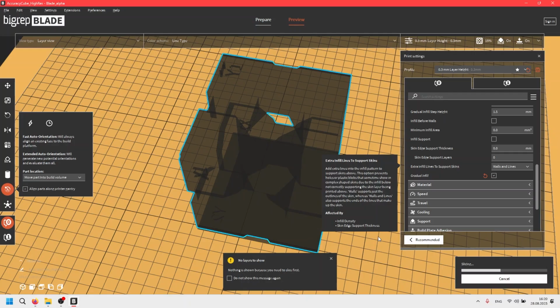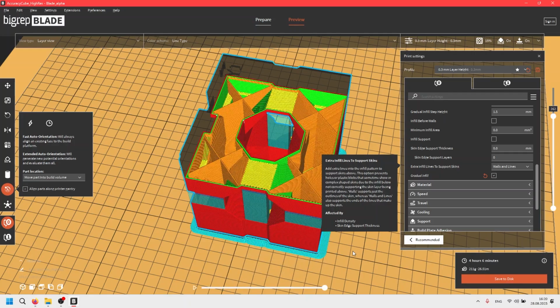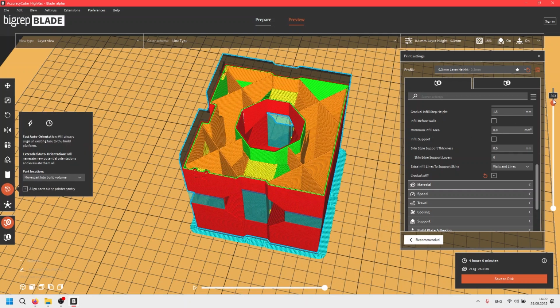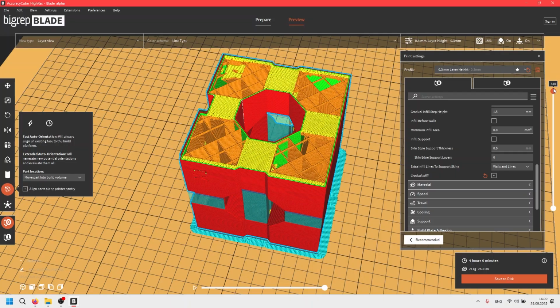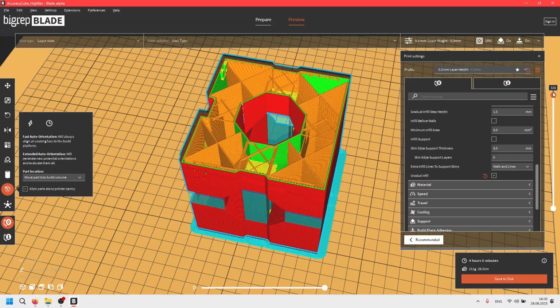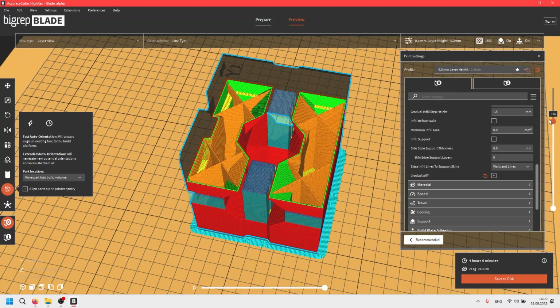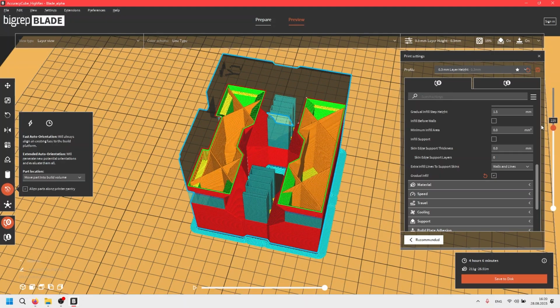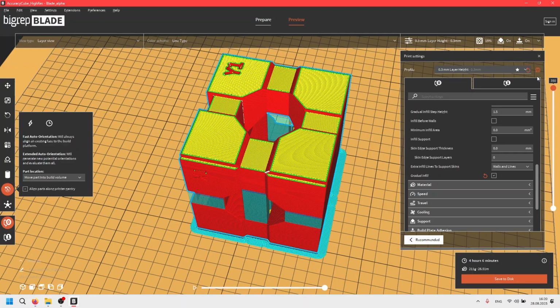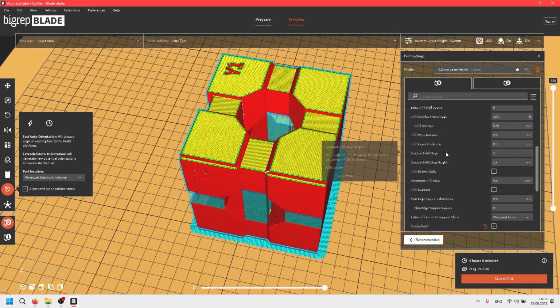And you'll see that the new infill pattern actually changes depending on how close to a wall or a roof you are. So when we're at the top of the part, we start moving down and the infill is very dense because we're near a wall. But as we get further into the middle of the part, the infill density drops. So in situations where gradual infill is possible and an option, it's recommended that you use it. Please be aware though, gradual infill will increase the slicing time a little bit.